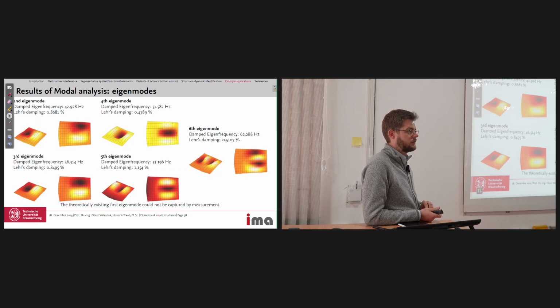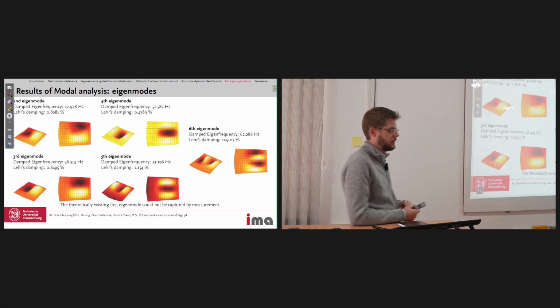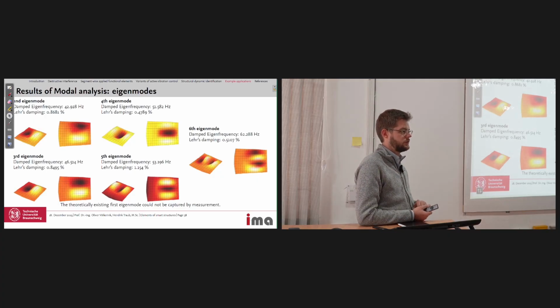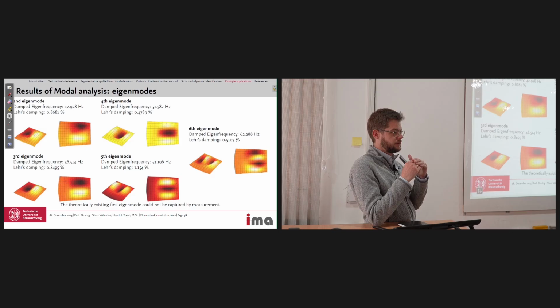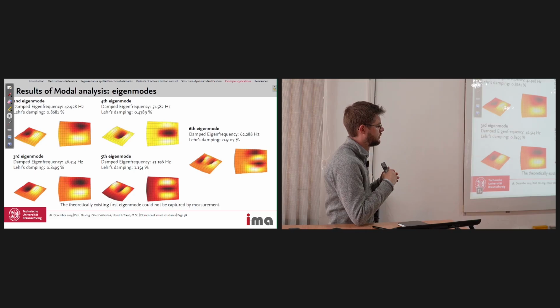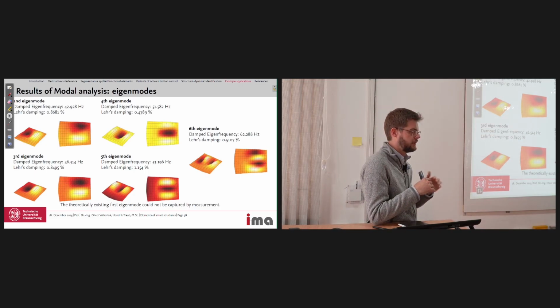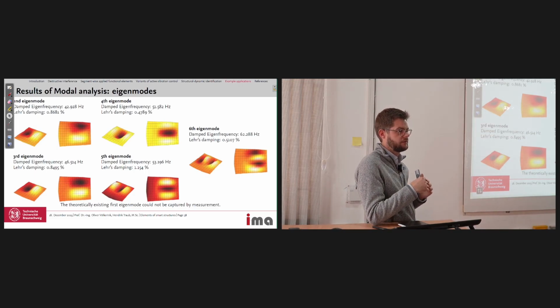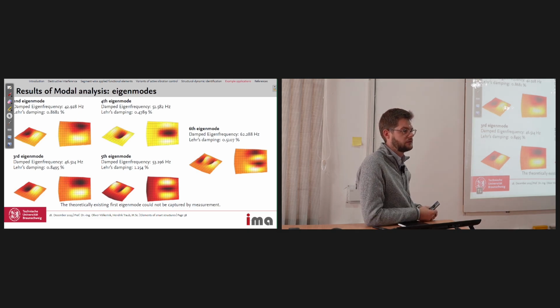We can calculate it, but I think the goal is to have this interface so stiff that it does not influence the transfer of the vibration from the actuator to the structure. So you would not use some kind of very elastic adhesive, but a rather stiff one that you can transfer really the vibrations without changing the behavior.